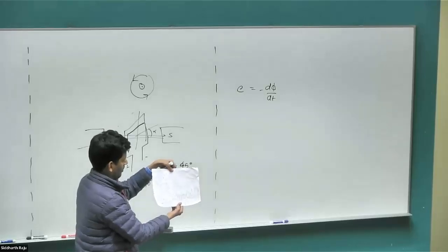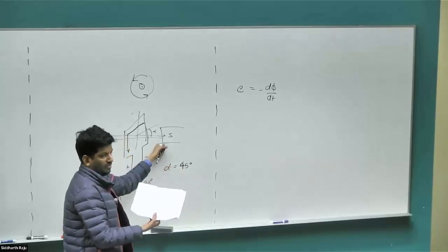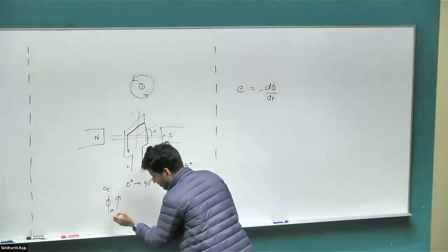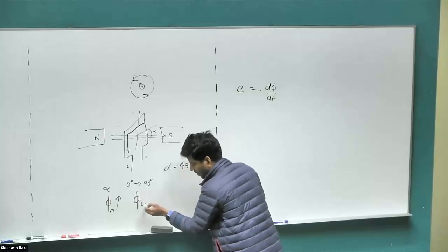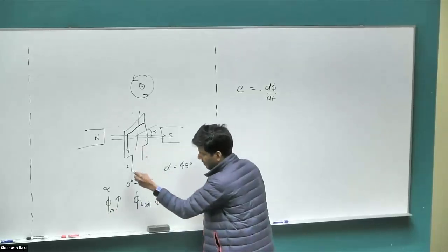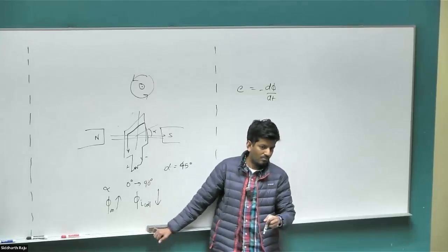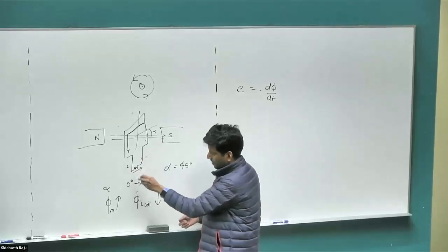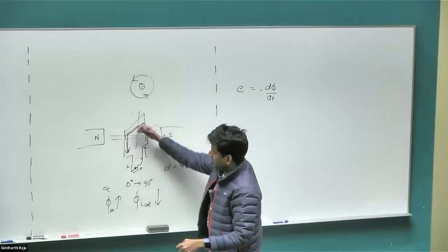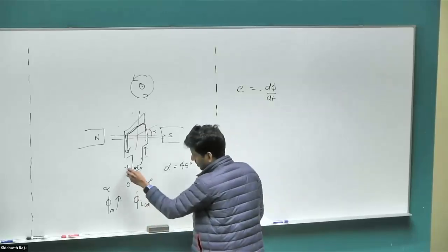So as the flux increases, because the coil is moving due to the external magnet, the current through this coil would be in such a way that it creates a magnetic field that is opposite to the external magnetic field. So as this flux increases, the current in this coil would be such that it would try to reduce the flux. So this is the flux due to the magnet, and the flux due to the current in the coil should be such that it goes down so that this increasing thing does not happen as this coil sees it. So if I were to put a resistance here, would the current flow in the correct direction for the polarity of the EMF that I've drawn? If this is positive, this is negative, oh, yes. Current would go through the correct way, right? So it would go from positive to negative in the external world. Internally, it has to satisfy KCL to complete the loop, right? So that's all the negative sign says. So the EMF that I drew here is perfectly correct.